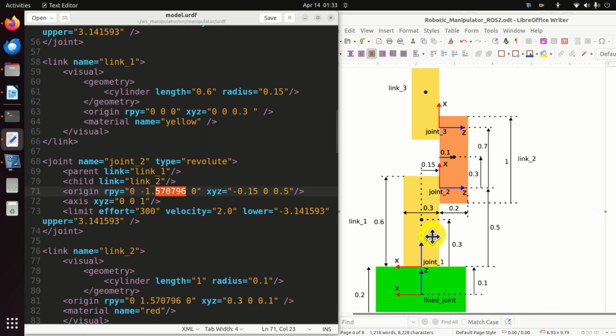And here you have to be very careful about what's happening, since we always want to keep the convention that our joints are rotating around the z-axis. Consequently, we need to define the rotation and translation between joint 1 and joint 2. These coordinates represent the rotation and translation with respect to the coordinate system of joint 1. We can see the following. We don't have rotation around the x-axis. However, what do we have over here? We have a negative rotation around the y-axis.